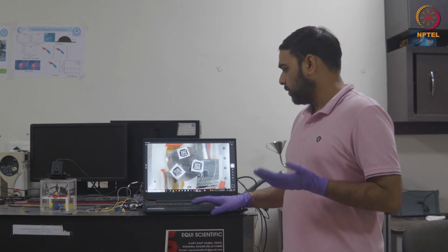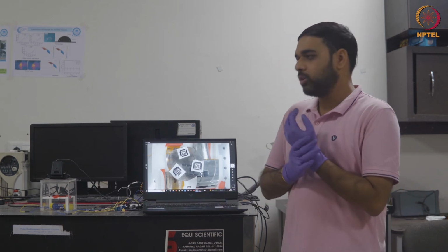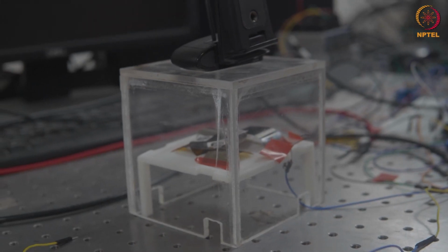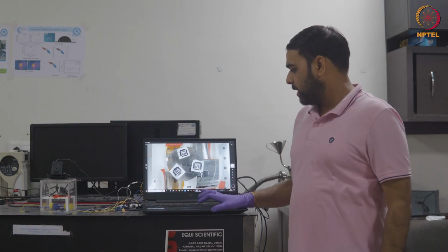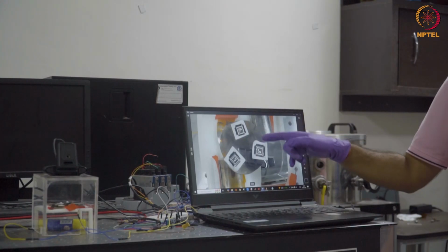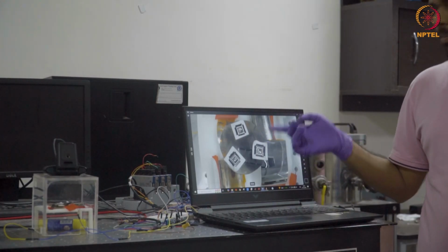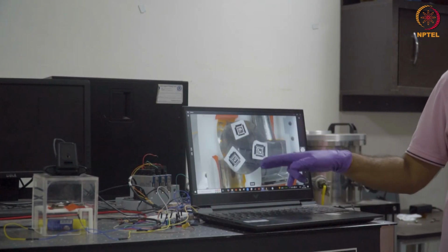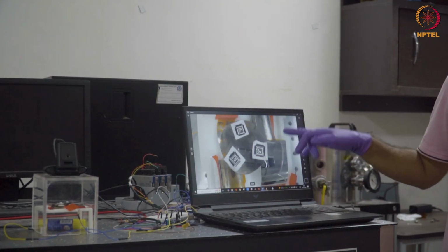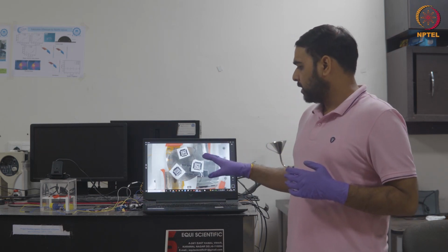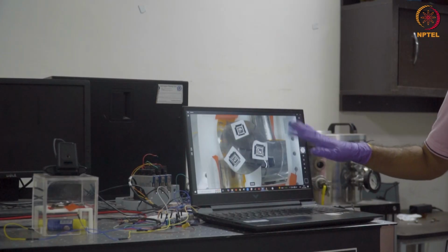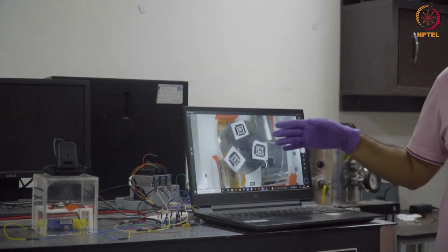This Stewart platform assembly is basically what we have learned in different studies also. Like, the base is a fixed base on which we have a moving platform, which in our case is a mirror, a lightweight mirror, in the central part. As you can see here, this is our central part, which is the movable platform or the mirror. And that mirror is supported using four different actuators. All the parts are NiTi SMA based, and they have been micromachined using laser energy of the fiber laser. In this structure, the mirror is being moved with the help of the motion of these four actuators individually or in combination.